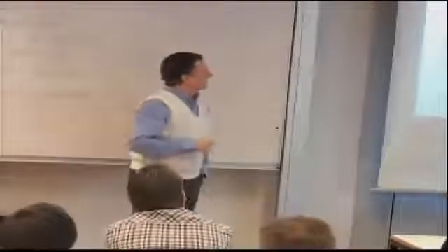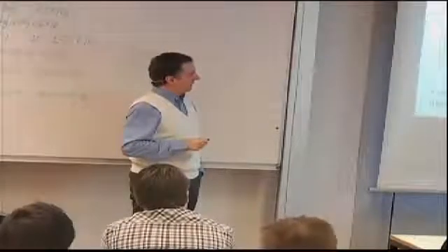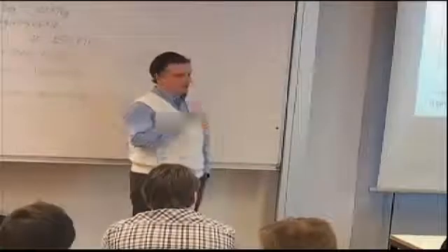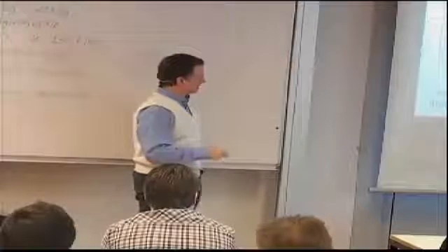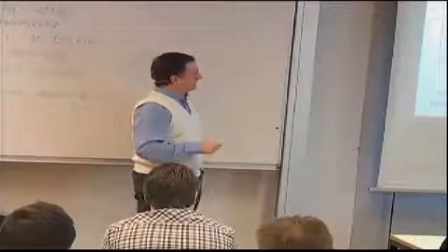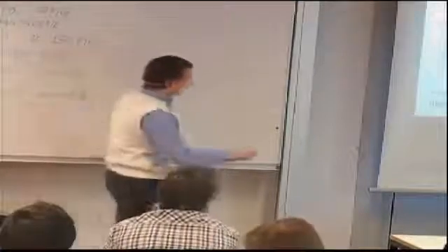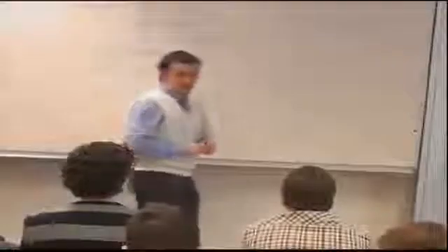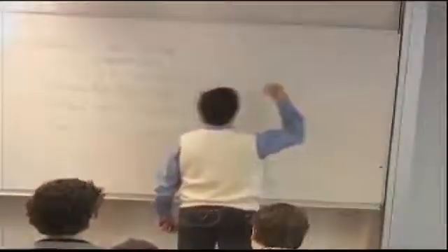So how does this therefore compare with standard materials? Aluminum, quasi-isotropic graphite epoxy, and then a graphite epoxy that would be more efficient than quasi-isotropic in compression. In fact, this is the stacking sequence given here. 45, minus 45, 0, 90 with an overbar, symmetric. 90 with an overbar means, for this course, that there's one ply in the middle and that's it. So the mid-plane is at the midpoint of that ply.